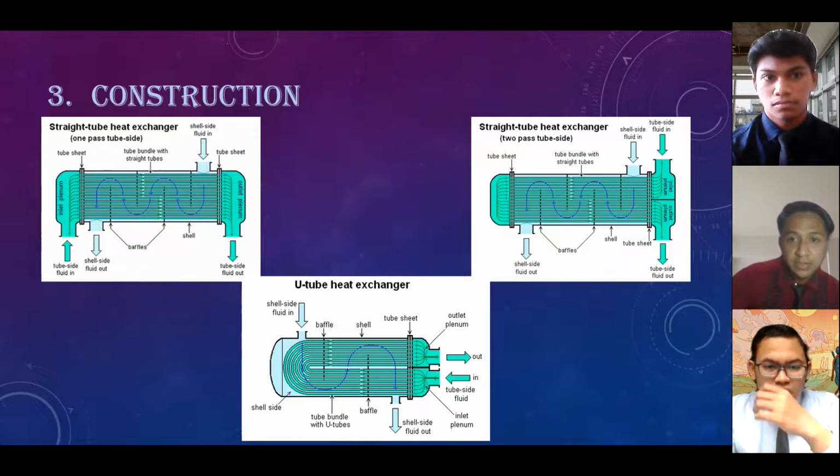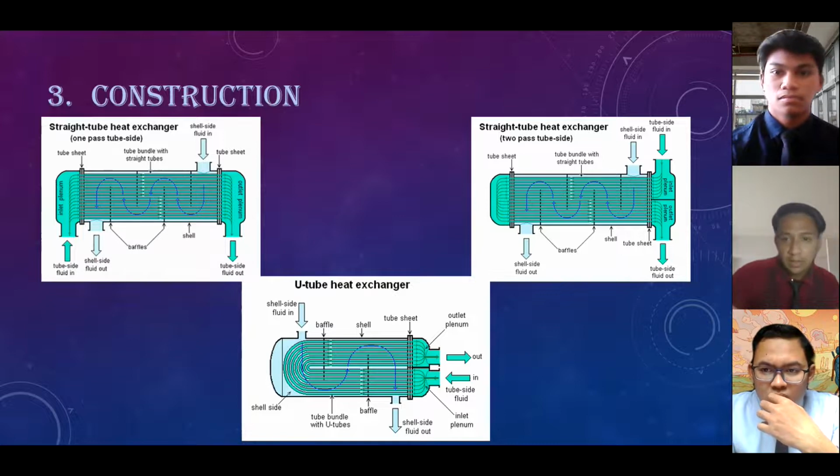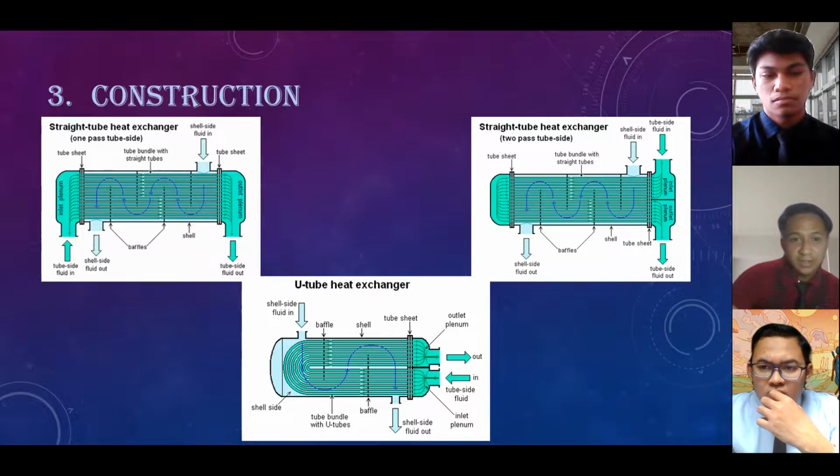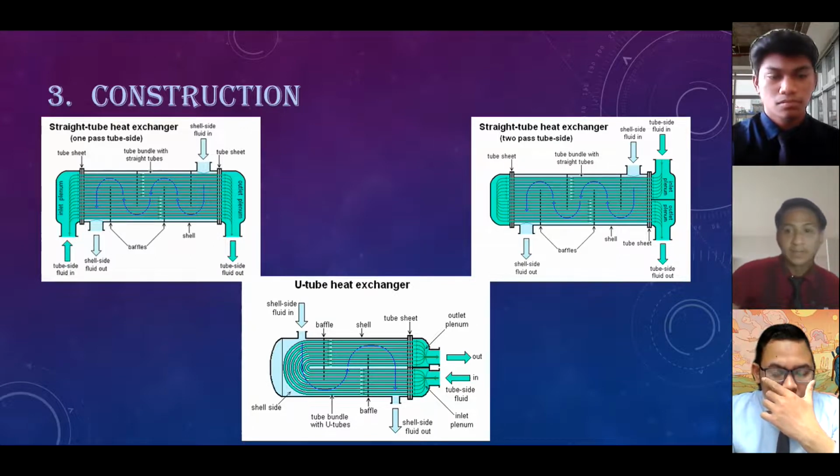Fluid does not take a shortcut through the shell side, leaving ineffective low flow volume. There is generally a higher log mean temperature difference between the hot and cold streams. Many companies, however, do not use two-pass exchangers. Often, multiple heat exchangers can be used to simulate counter current flow, instead of a single large exchanger.